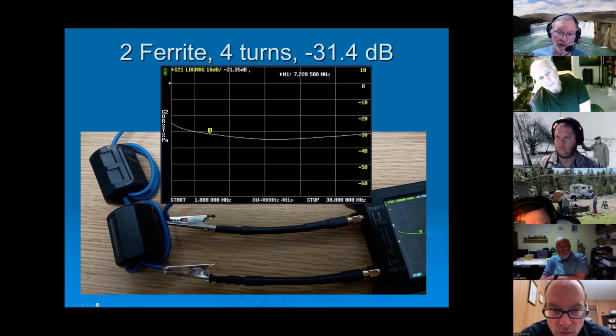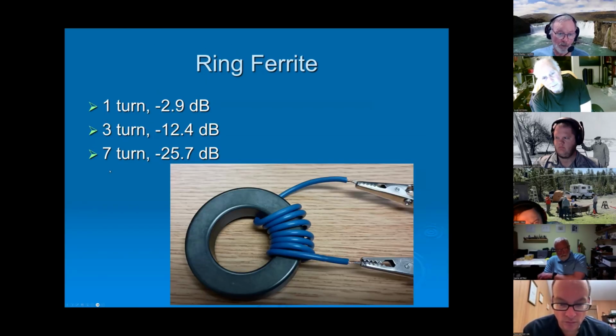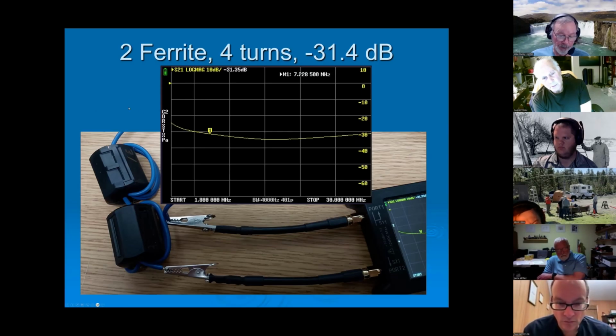Like, when I'm running some serious power, that RF gets into every single monitor that I have and scrambles things, gets into every single USB cable, and I have a ton of those things. And so many times I have to use 2, 3, and 4 ferrites in order to null out all the RF that gets into everything. Okay, so that's dealing with these clamp-ons.